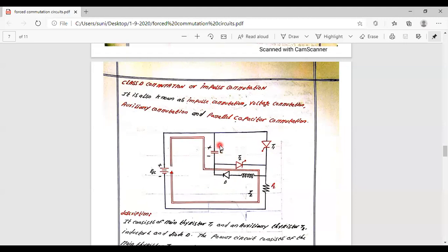So what will happen? It is positive. If this diode is not placed and simply an inductor is placed, the capacitor has a discharge path provided from the load to this. Then there is no commutation provided to the main device. To provide the commutation or reverse voltage to the device, this particular potential should be blocked, and that is going to be done by this diode, which is considered a blocking diode.